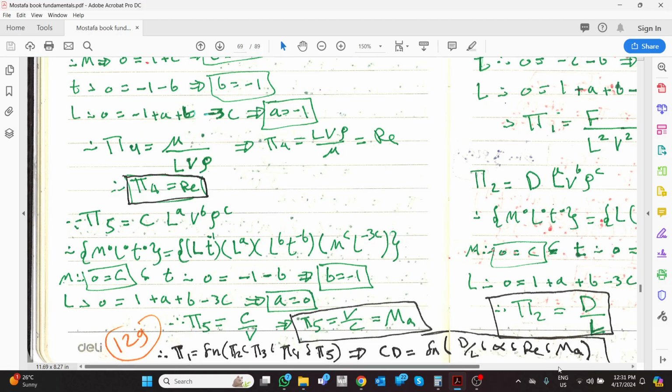And we know the velocity of the rocket divided by the velocity of sound, in case of temperature change, should be constant. The Mach number should not change. For example, if I change from air to argon, R changes, gamma changes, so C changes, so you need to respect this effect as well.